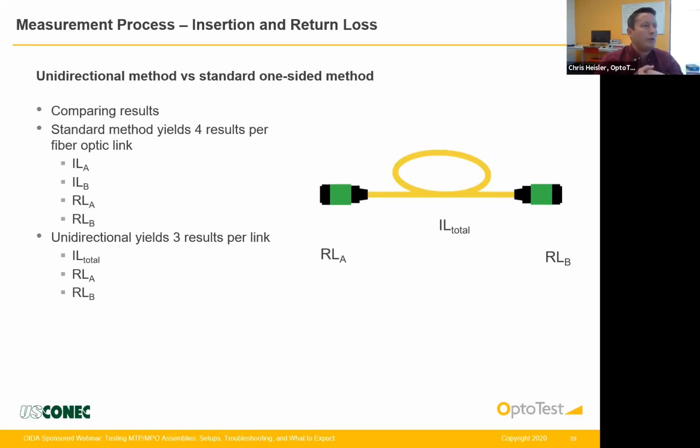It's a good question. If you are measuring two reflections that are very close to each other, those two reflections add to each other. Let's assume you have a 50 dB return loss on both sides of that DUT. If you add those two reflections together, you don't add 50 dB with 50 dB, that would give you 100 dB. You need to convert those two values back to a linear value and then add them together, and then you'll get the resulting actual return loss value.